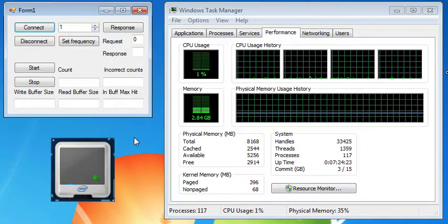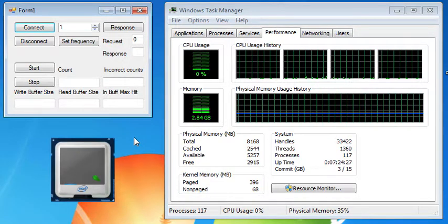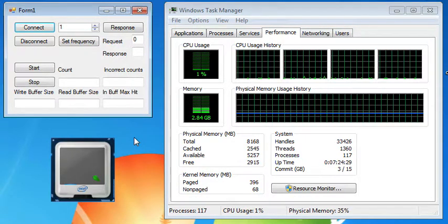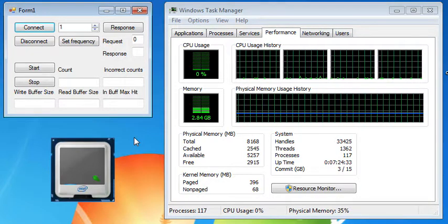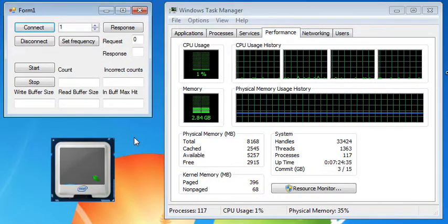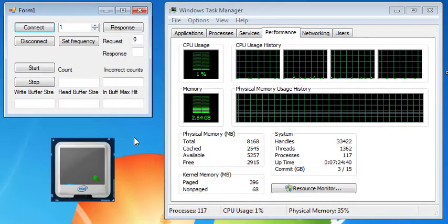This was okay during initial testing because of small volumes and low frequencies, meaning the event handler could trigger fast enough to clear the buffer. However, when sending multiple values of information, the buffer will fill. This is because the PC end will only read the first line. Over time, this causes the buffer to fill to an infinite value, hence infinite latency.